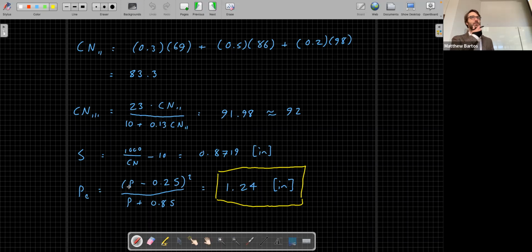So what's another thing that this implies about the curve number method? What does it imply about the amount that infiltrates over time? When you're simulating excess precipitation using the curve number, the available space in your soil volume only decreases over time, because you're adding more rainfall in and it doesn't have any way to get out. So the infiltration capacity of your soil essentially always decreases over time. Another important fact to remember is that the curve number method is not suitable for continuous simulation. It's only suitable for simulating a single rainfall event.